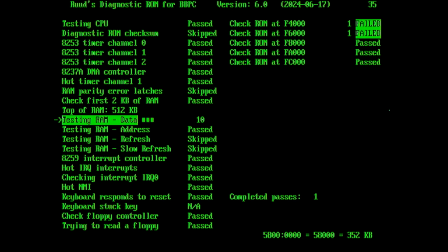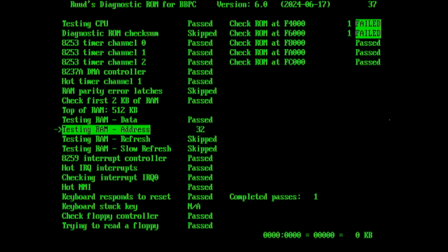So this appears to be working. The keyboard tests are working, and the floppy disk controller tests appear to be working, although when I actually looked at the logic analyzer diagnostic output, it does appear that not all of the DMA related signals are working properly there, so I'm going to have to look into that. But it's certainly given a good sort of stability test.